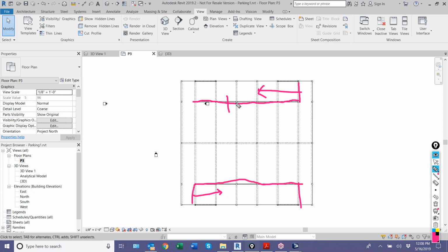Okay, and the beams, there's a column. So if I blow this joint up right here, we're going to have a column with a beam which frames to center line of column. And then the opening actually stops at the face of the column so that we can mesh this joint and it's meshed through.